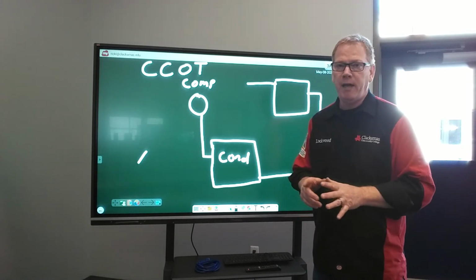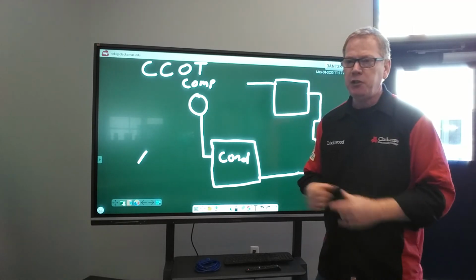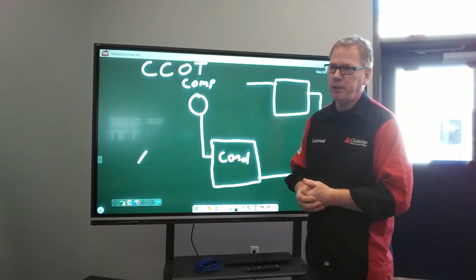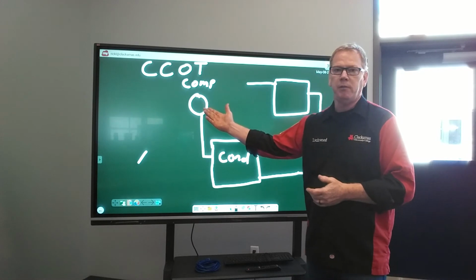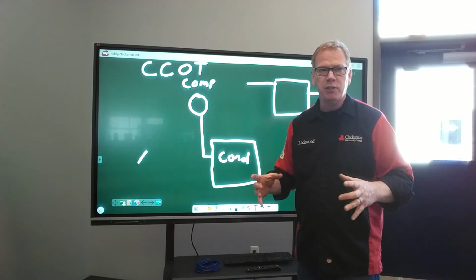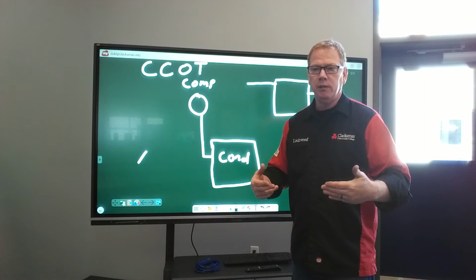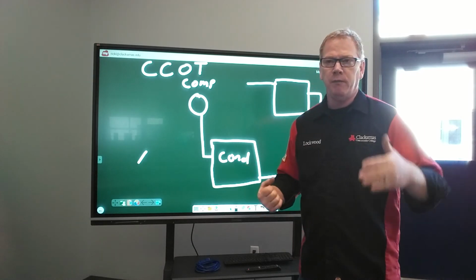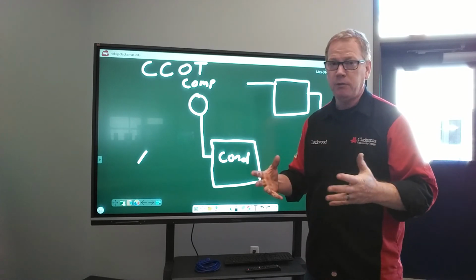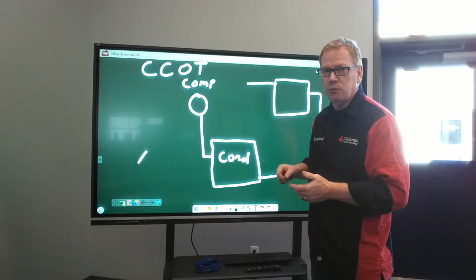What we don't want to have happen is send liquid refrigerant back to the compressor. If we do that, we can't compress a liquid. We can compress a gas, but if we try to compress a liquid, we're going to damage the compressor. It's no different than you filling up the cylinders in your internal combustion engine with water or coolant, and you try to start that motor. You're going to what's called hydrolock. You have something that cannot be compressed and you're going to try to compress it. So something's going to break. So we need to make sure we don't have liquid refrigerant getting back to the compressor.